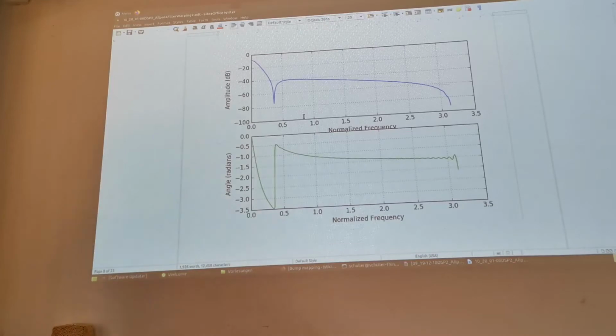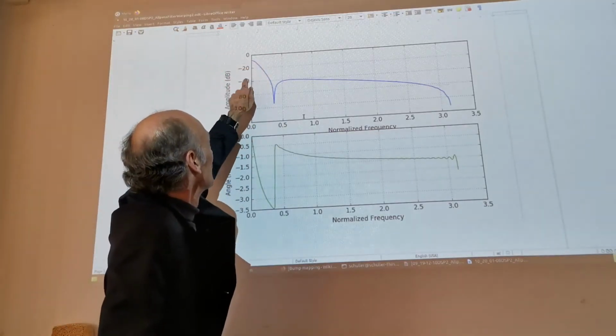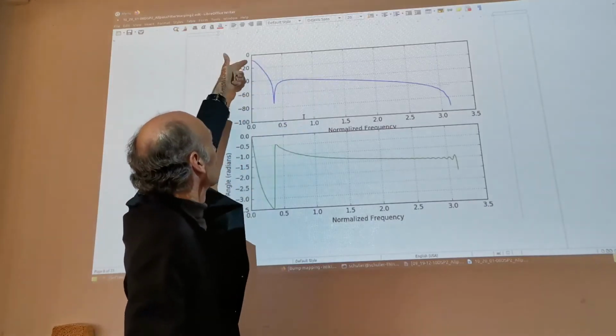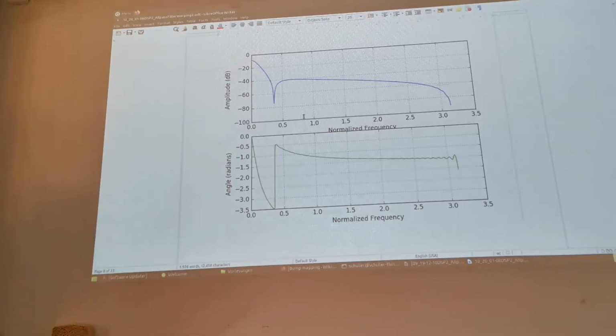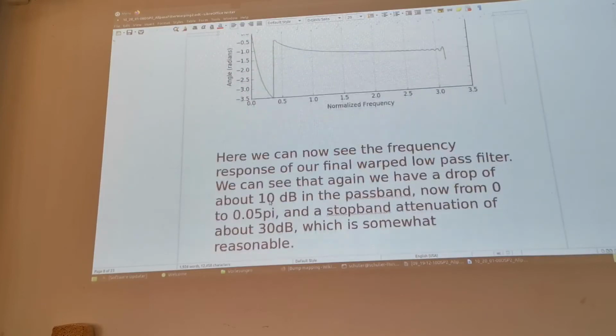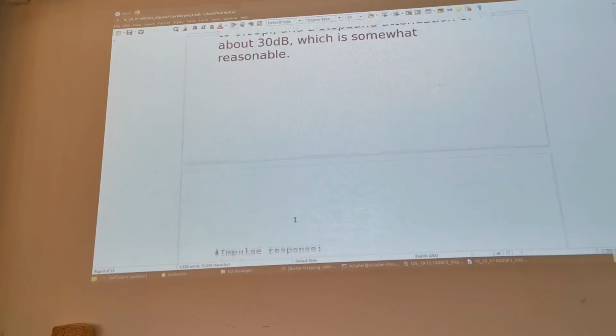So now you can see it actually looks quite good. We have a narrow pass band, here you have a transition band, and then we have a stop band, compared to a pass band, of maybe 50 dB. So this is now actually a useful filter, right? A very narrow band, useful low pass filter. A very nonlinear phase, but that's because now we have an IIR filter. That's why the phase became very nonlinear. So it's actually not so bad a filter.